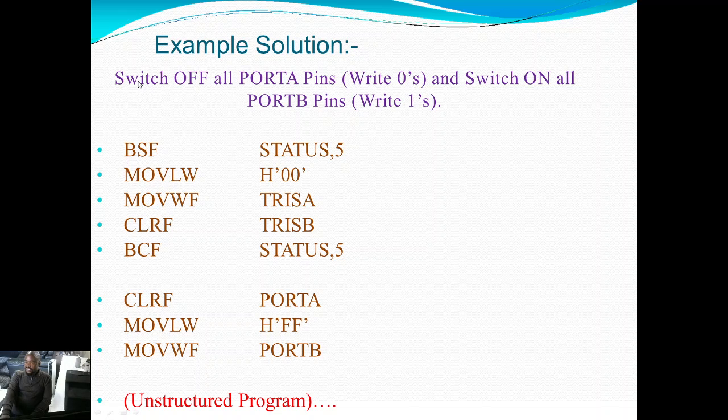And in this case, we were asking you to switch off all port A pins and to switch on all port B pins, meaning that you have to configure all these pins as outputs before you can switch them off. By default, all your microcontroller pins are inputs, meaning you have to configure them. If the program required that your pins are inputs, since they are inputs by default, you don't really need to reconfigure them as inputs. But it is important that you configure your pins so that when you execute your instruction, you know that you have configured your pins in the right configuration before you read or write to them.